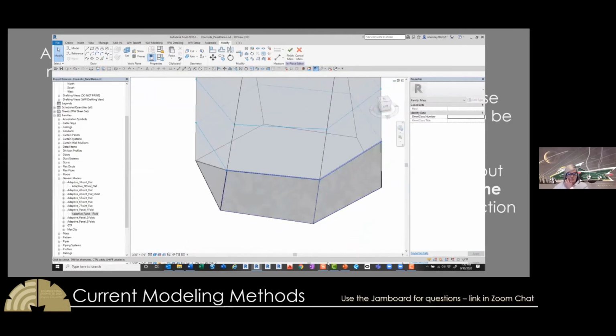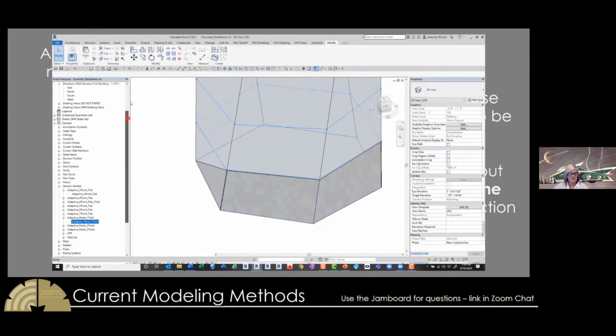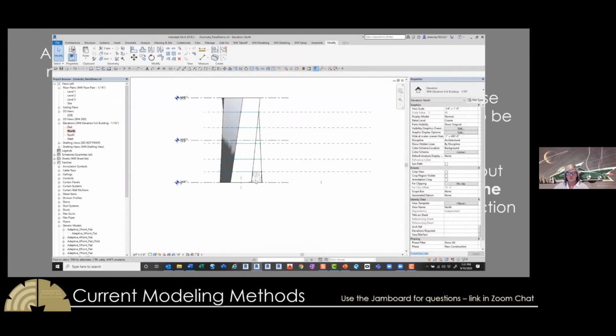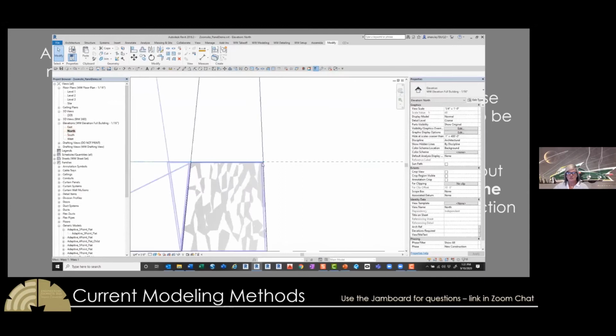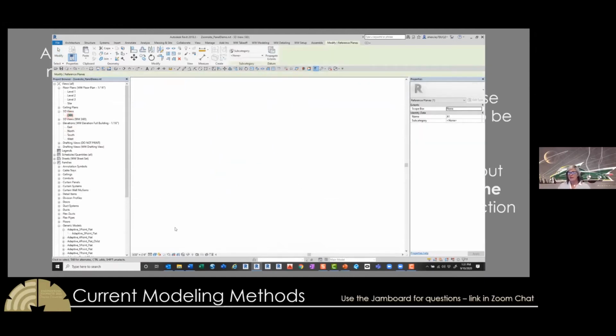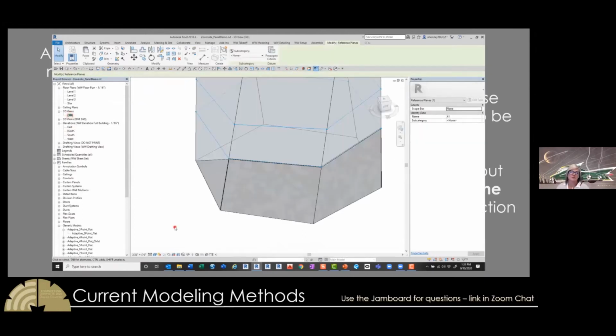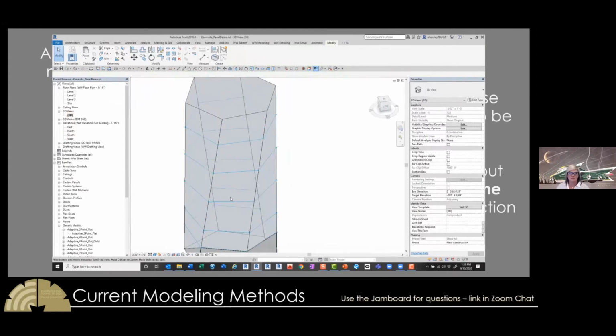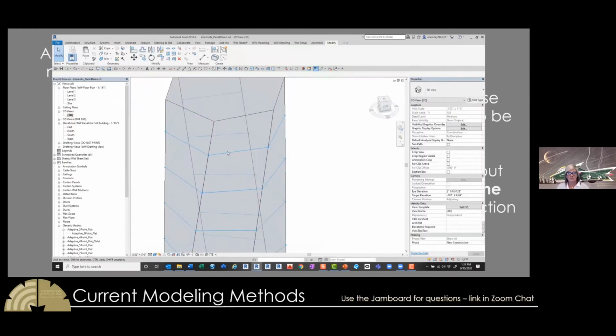All right, so then we'll go ahead and see, what do I have next in this one? Okay, I'm going to go to the elevation and I'm going to adjust that joint. This is where the layout can pay off. If it ends up the architect wants to move that joint, all we have to do is move that reference plane and the panels will shrink and grow with it. So even though there was more layout, it's not a total loss. You can still make some updates later. And we'll put one more panel up here at the top.